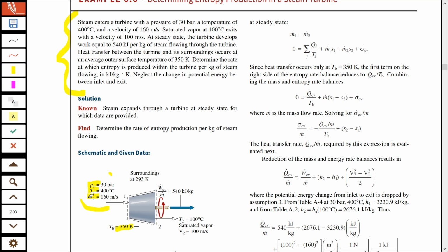No, not volume. Sorry, this is the velocity, 116 meters per second, and temperature at the outlet T2 is given, velocity is given, and you can see that the velocity has decreased, and the phase is given, so it's saturated vapor. It's saturated vapor, and it must be written. So saturated vapor exits at the outlet side. Steam is written there.